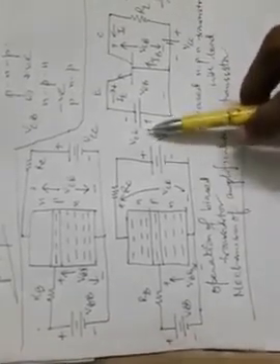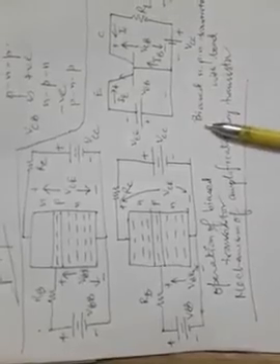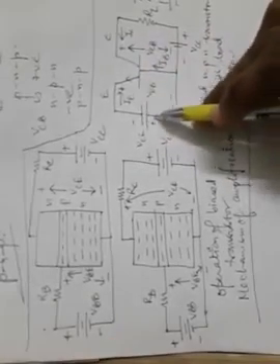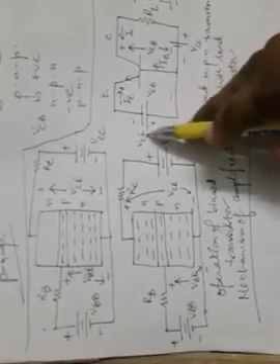In this diagram you can see the voltage source VEE is connected in such a way, since the BJT is NPN, that the N side is connected with the negative terminal of the battery and P is connected with the positive terminal, so the VEE source is making the base emitter junction forward biased. Similarly, the collector is N, and that N is connected with the positive terminal of VCC, which means the source VCC biases the collector base junction in the reverse direction.